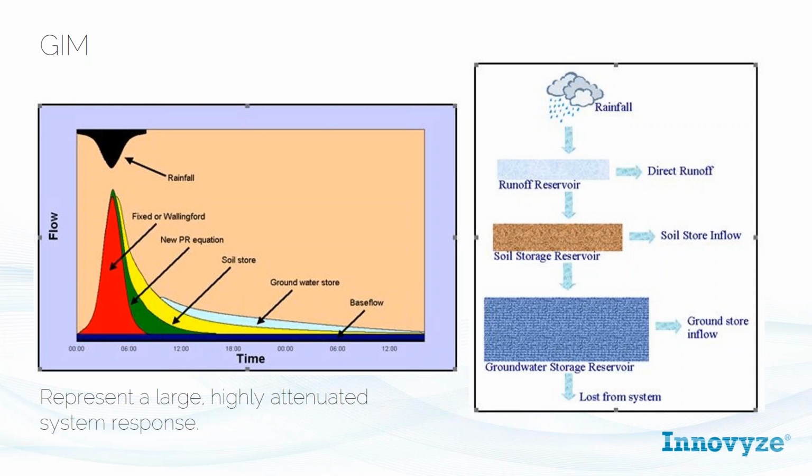It originates from groundwater or rural or underdeveloped parts of the catchment. With runoff in particular, there is some rainfall which enters the sewer and some which does not. So the key to utilizing the GIM, as we call it in InfoWorks ICM, is that it allows a proportion of the rainfall which does not get into the sewer as runoff initially to get there by other means.